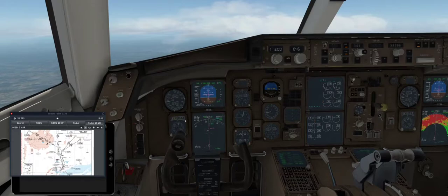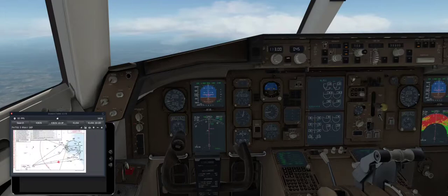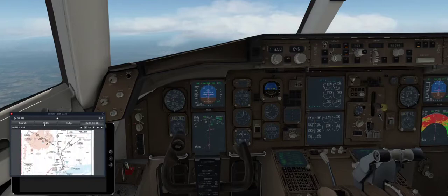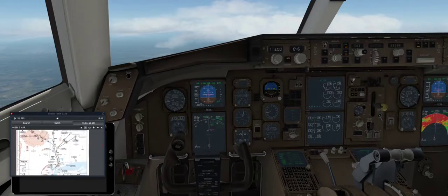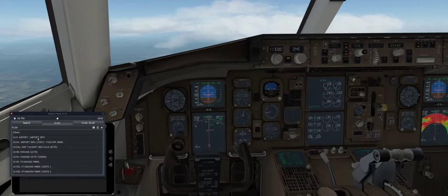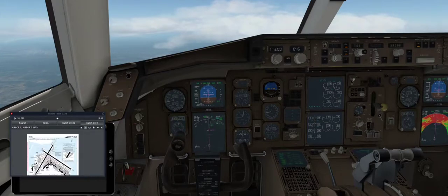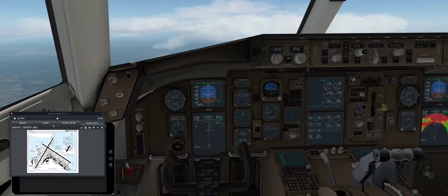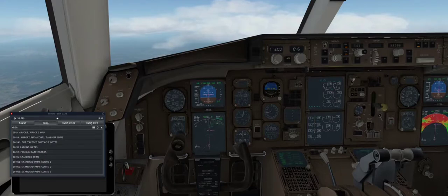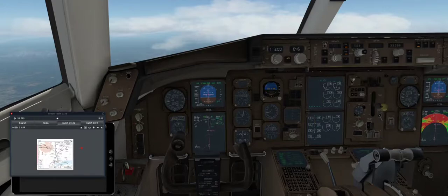And now we are headed basically west. Because this departure took us this way, and now we've finally been headed in the direction we want to go, I'm going to go ahead and close that chart, as well as the whole KBOS. So we know we've got the arrival up. We know at some point we're also going to want an airport diagram, so I get that ready as well. And we know we're going to need an approach, but we don't know which one yet, so we'll just hold on to that.